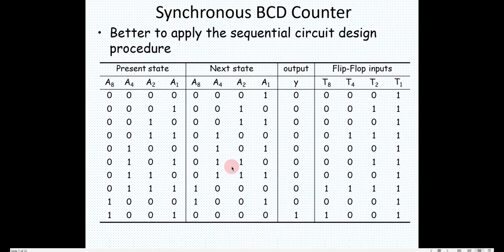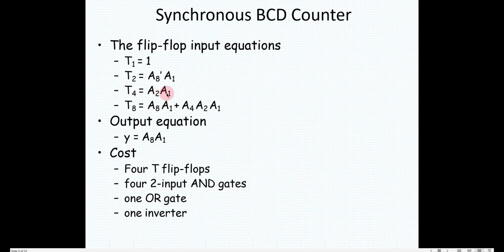So what about the next one? Here, if you see, 1 1 is making a 0. So I will take an AND of these two, so that there is a toggle happening from here to here. Again, 0 0 no toggle, 0 1 no toggle, 1 1 it is again making a toggle. So simply A4 I can write as AND of A1 and A2. So this is A1 and A2, right?